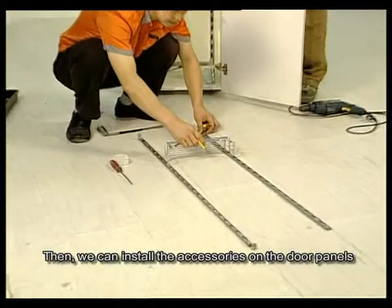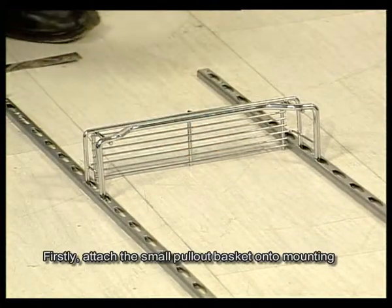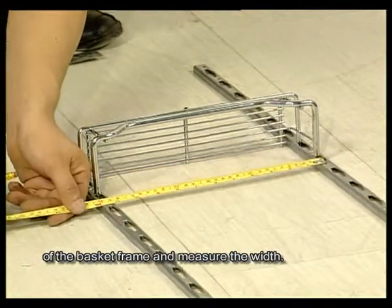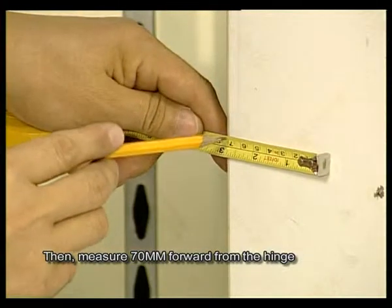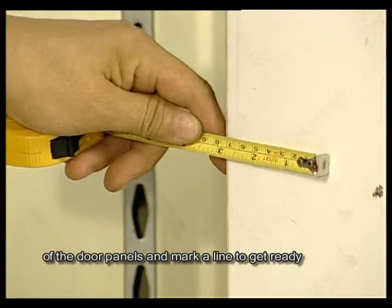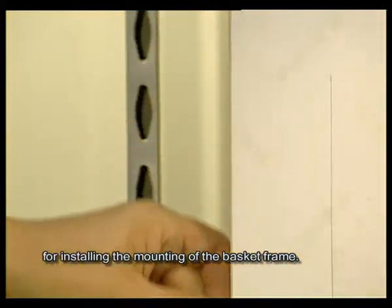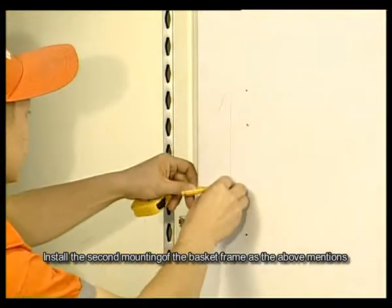Then we can install the accessories on the door panels. Firstly, attach the small pull-out basket onto the mounting of the basket frame and measure the widths. Then measure 70 mm forward from the hinge of the door panels and mark a line to get ready for installing the mounting of the basket frame. Install the second mounting of the basket frame as mentioned above.